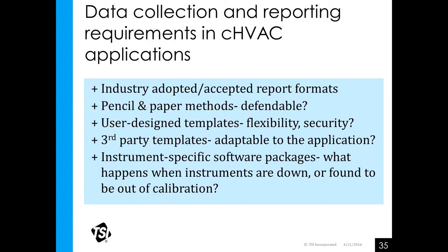Are they adaptable to the application? Can changes and adjustments be made in that template, or are you stuck with what you bought and don't have the ability to report things the way they need to be reported? At a minimum, there must be date, time, parameter, instrument used, serial number or numbers, and the reading or readings that are used. If you don't have that, you're shooting in the wind to be able to justify a critical HVAC job.